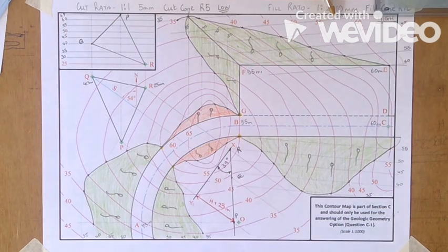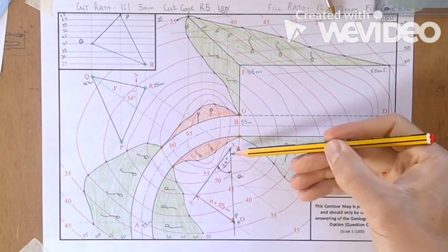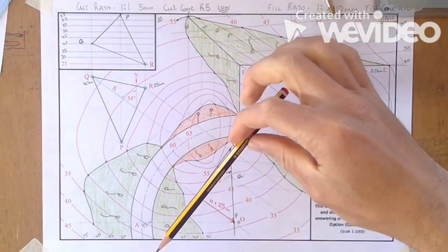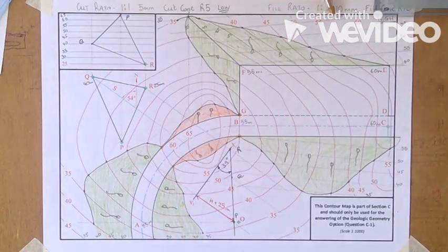The easiest way to do this is if we look perpendicular to the edge view of the top surface of the stratum of ore that we already have, draw an auxiliary plan view, and then take our measurements from our previous XY line back to our plan view. So we'll print a datum for that.